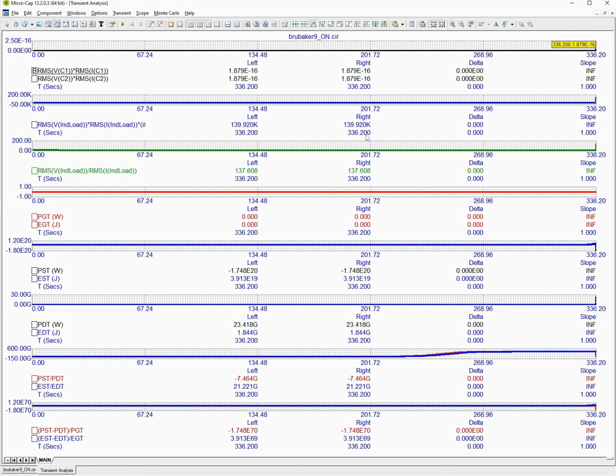I mean, if your target, see now, my EV from 2002, the RAV4 EV, requires at full throttle around 67,000 watts. So 140,000 is about twice what you need, which is not bad wiggle room to deliver slightly more.